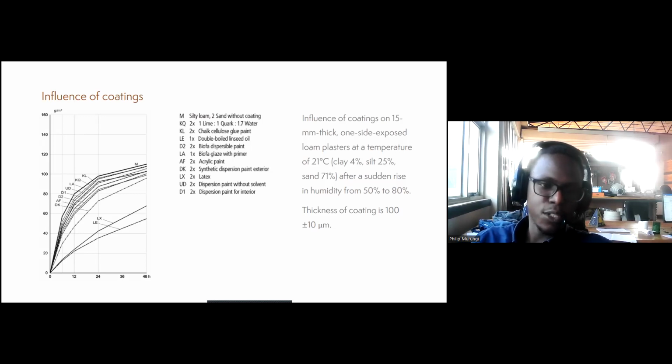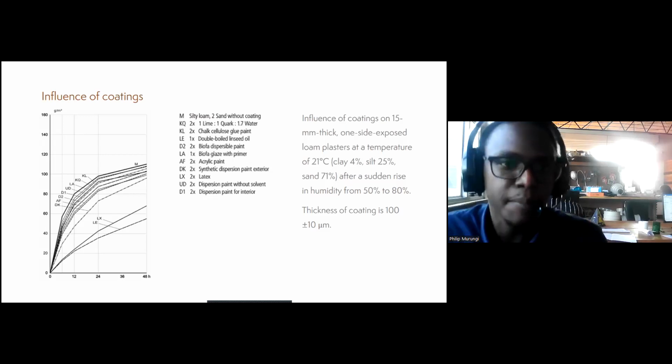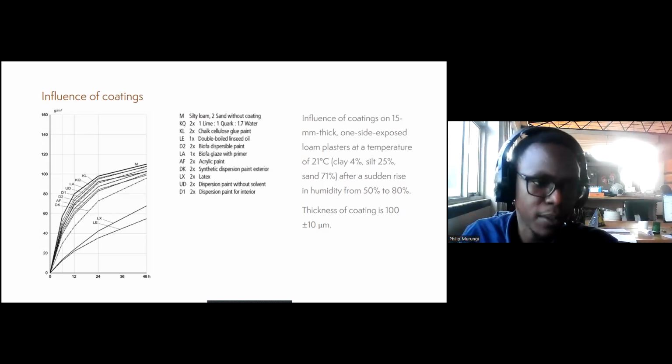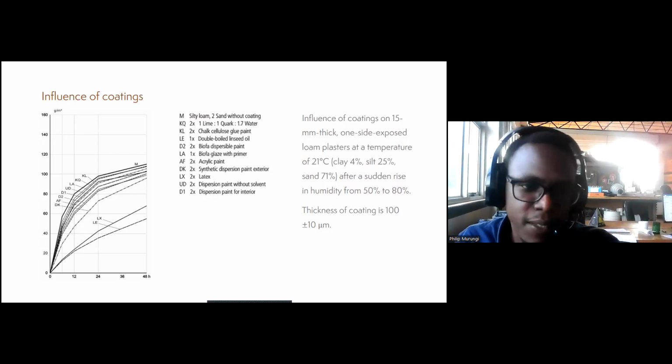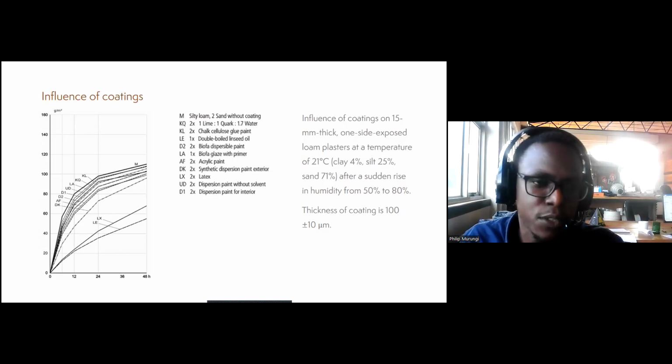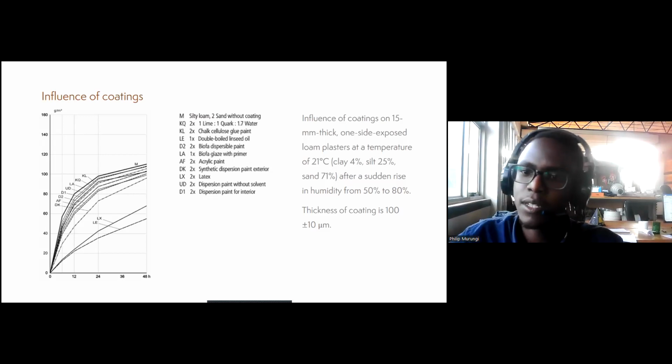And what you'll see is that your acrylic paints, well, they lower the ability of your wall to breathe, basically. Your synthetic paints do the same. Your latex substances do the same. Your primers do the same. The materials which don't have such a pronounced effect, maybe your linseed oil is not so bad. Linseed oil is actually bad, sorry. Maybe your limes. So lime is good, and lime plasters are good.